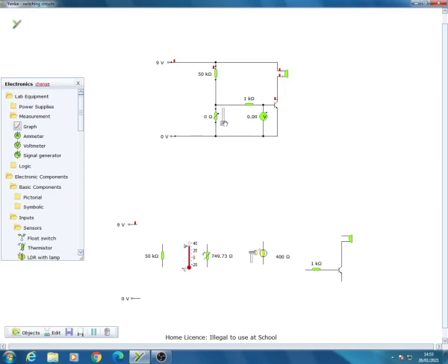But what you need to know is as I move this slider up and I get more resistance down here, the voltage goes up here. So the voltage between this thing here called the base and the 0 volts is going up. And when it gets to 0.7, the transistor switches on. And when the transistor switches on, it means that the load, this thing up here, so in this case it's a buzzer, the buzzer will switch on. So by varying the resistance down here, I can switch this buzzer on and off.